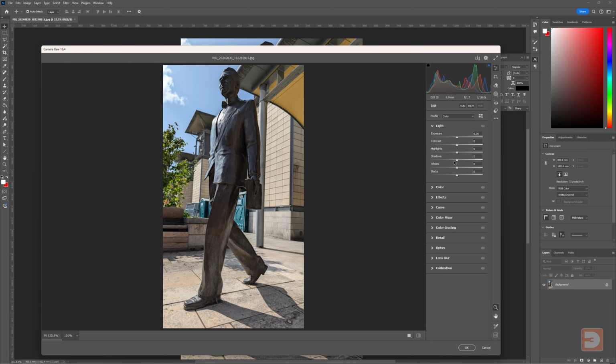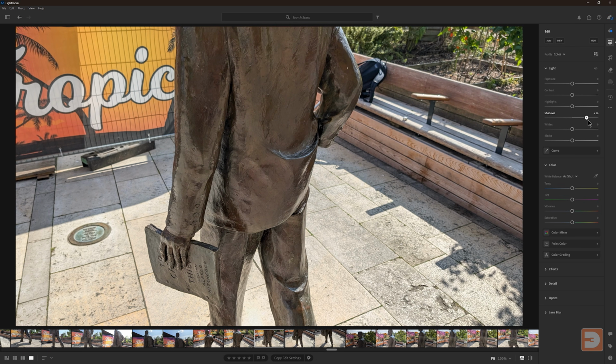Photogrammetry software uses the information in the image's metadata, so it understands the camera, the lens, and the settings that we used. If you were to crop an image, it's then going to confuse the software further, and it may try and apply unnecessary corrections. Whilst you shouldn't make any structural changes to your photos, you can adjust things like brightness and contrast for better software recognition. Editing your photos in Photoshop or Lightroom can ensure better exposure and consistency across the images. Lightroom is especially efficient for editing large batches of photos, saving you time and ensuring a cohesive look.